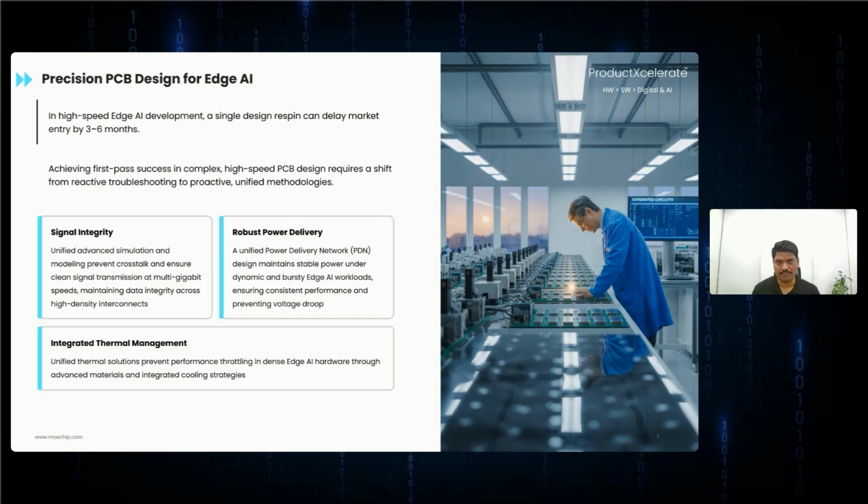For example, memory fails in calibration, PCI Express lanes drop packets, the PDN sags, thermal chokes every time the AI accelerator kicks in. Why? Because in an edge AI design, you're packing DDR running at gigatransfers per second, PCI Express Gen 5 highways, MIPI camera and display lanes, and 15-watt SoCs all into the same cramped stack-up.